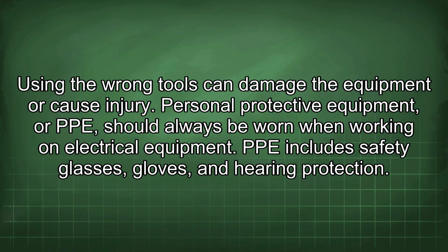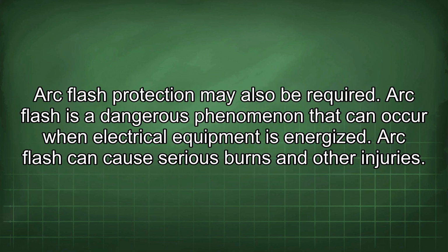Personal protective equipment, or PPE, should always be worn when working on electrical equipment. PPE includes safety glasses, gloves, and hearing protection. Arc flash protection may also be required. Arc flash is a dangerous phenomenon that can occur when electrical equipment is energized. Arc flash can cause serious burns and other injuries.